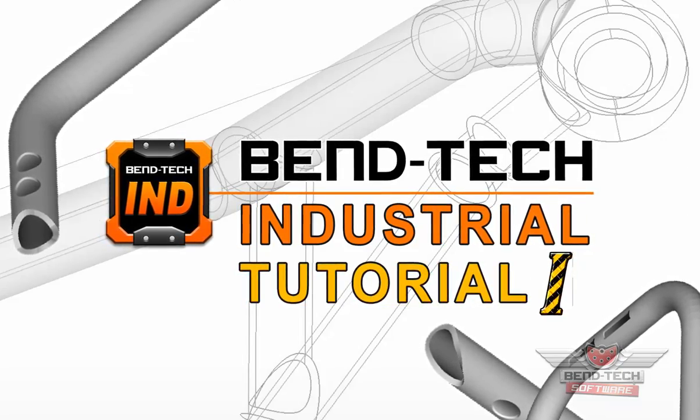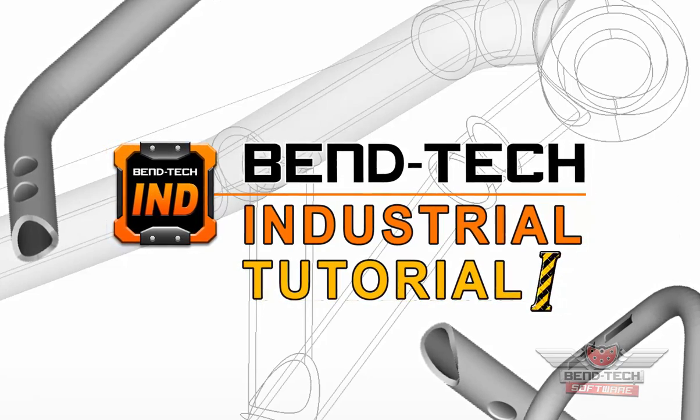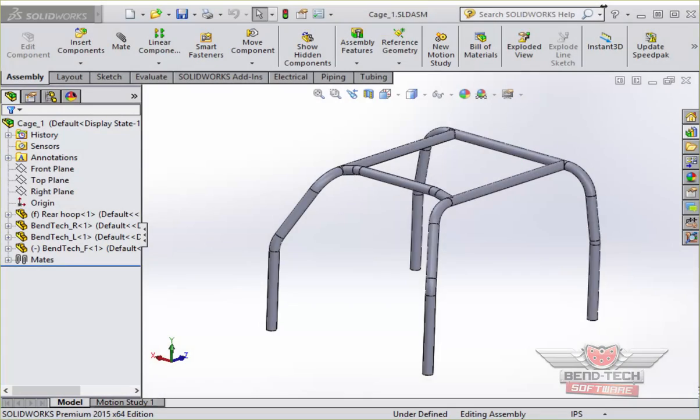Industrial solid model importing will take a solid model design in STEP or IGES format and prepare it for fabrication with your machine. In this video, we'll take an IGES file of a roll cage designed in SolidWorks and prepare it for fabrication in DXF format.